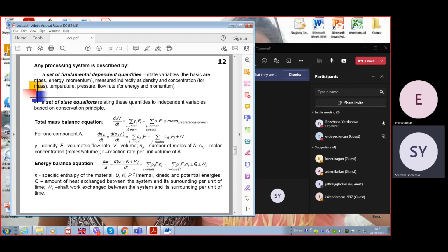So this is the energy balance equation. In case of constantly stirred tank reactor, no kinetic, no potential, only the disbalance of flow and this additional heating from serpentine makes the equation. This equation can relate temperature with heating agent, while the first equation relates level with flow rate at inflow or at the outflow.